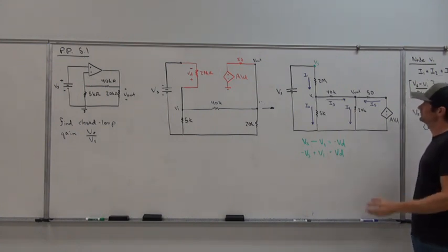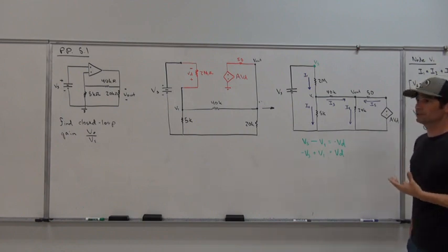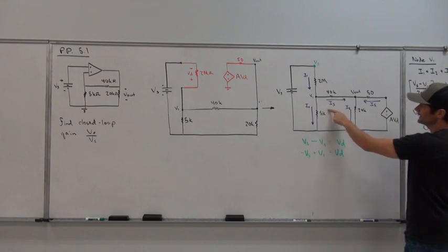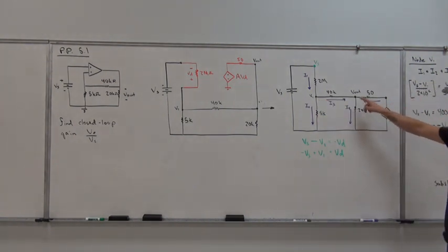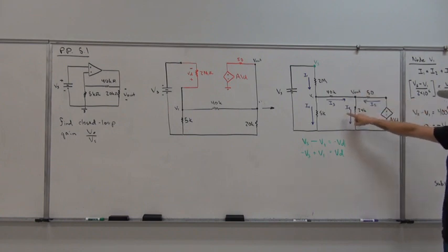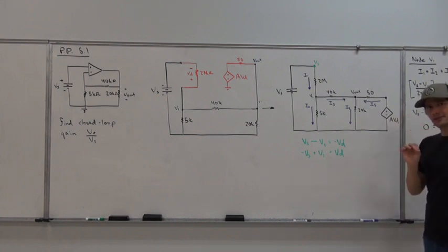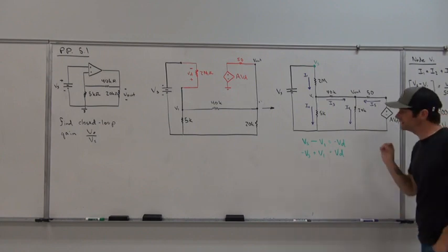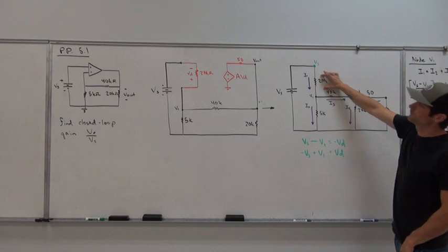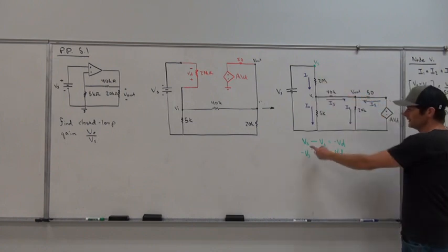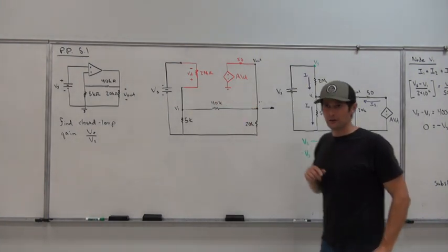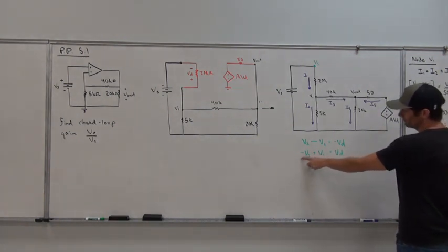I assigned our currents in here because we're going to solve with nodal analysis. I1 is coming into node V1, which I've labeled, and then I2 and I3 are coming out of V1. Over here, I5 goes into V naught and leaves V naught as I4 through the 20k ohm resistor. Because we'll use this later, let's relate, based off I1, how we can rewrite Vs and V1 in terms of Vd. The voltage across the 2 mega ohm resistor, negative to positive, is Vd. So Vs minus V1 is equal to negative Vd, based off the polarity across that resistor. Rewriting, Vd is equal to V1 minus Vs.